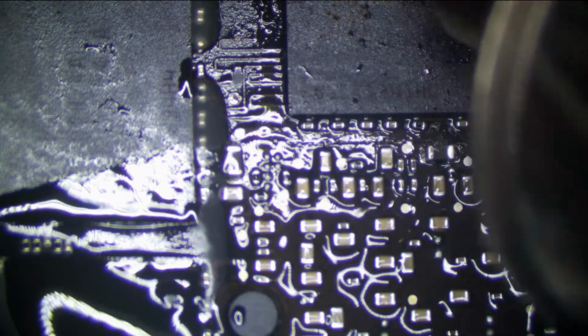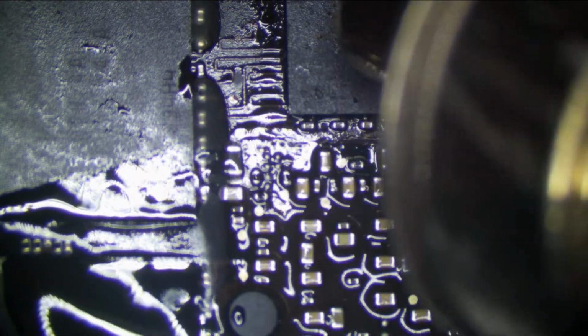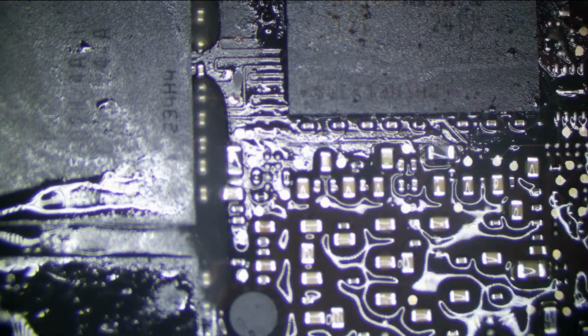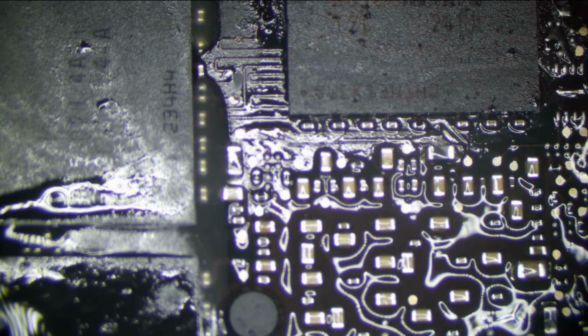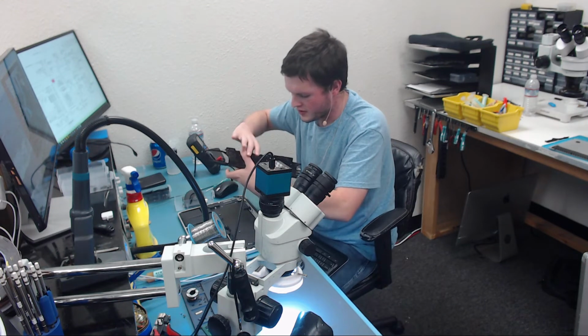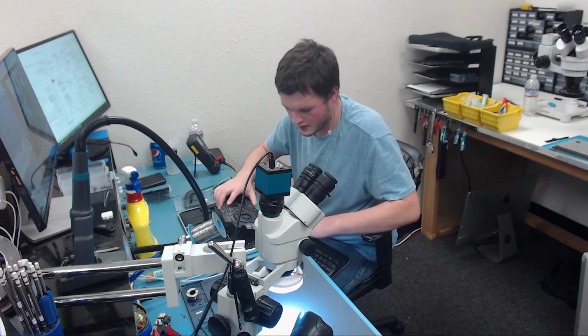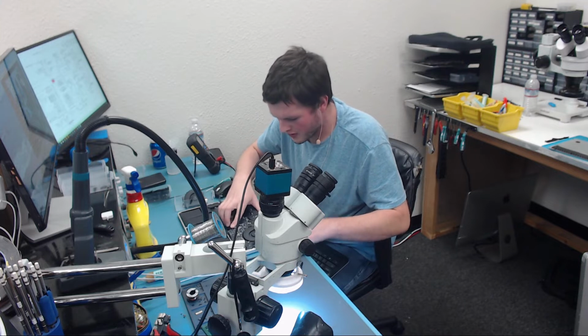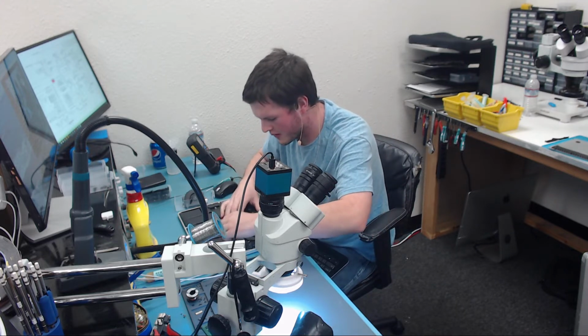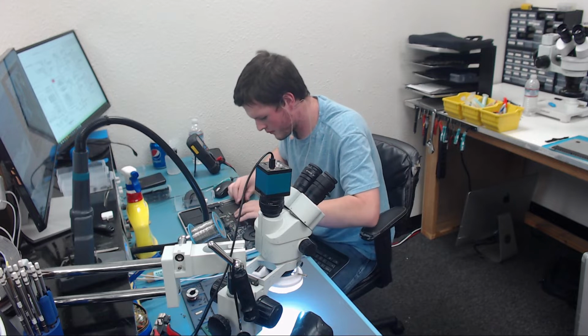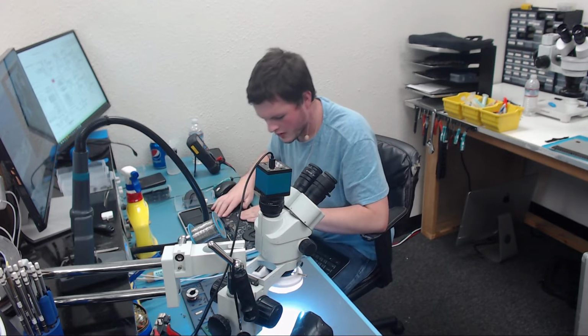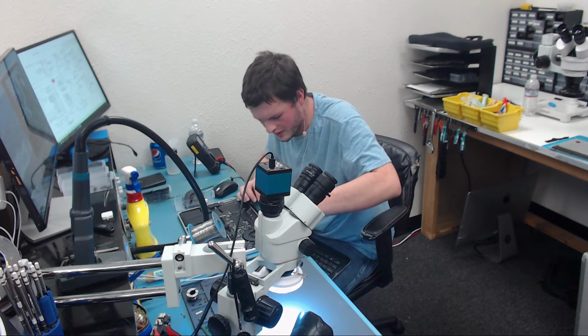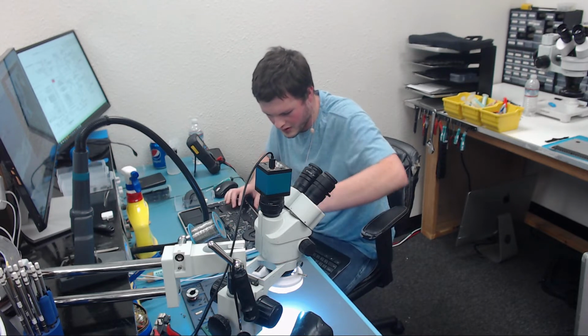I don't actually think a lot got under there, so I think we're good. That should be good. Now we're going to let it cool down, and then we're going to test in a minute. Alright, let's put this board back in now that it's cooled down, so it won't burn up as soon as we turn it on. That wouldn't be fun. I don't want to deal with a burned VRAM chip. It doesn't have to go in all the way, just enough so you can plug in the screen. That's all we really need.